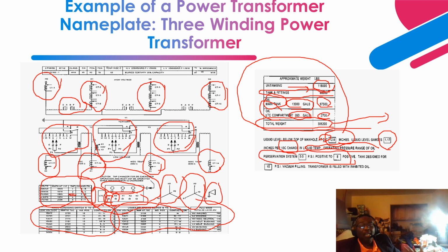Right. Okay, so if you're filling the transformer under vacuum, remember I made mention that we fill the transformer under vacuum to mitigate gassing, right? Gassing, oil bubbles that can degrade the transformer insulation system, right? Okay, so a vacuum is maintained, and this is the amount of vacuum that the manufacturer is telling you to maintain, right? To prevent that gassing and bubbling that can degrade the insulation system when the transformer goes into operation.